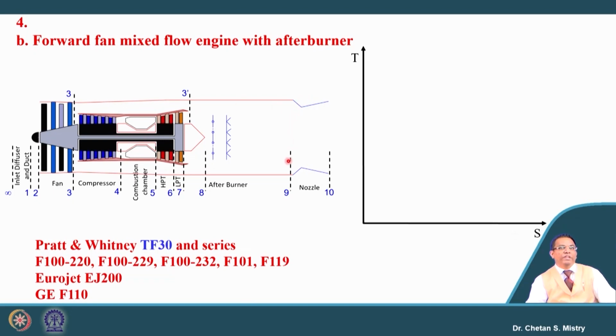So, in place of that, we will try to increase the temperature at the entry of the nozzle in such a way that the expansion that will be happening inside the nozzle will be giving very high velocity. And in this case, we are not having any rotating component, and that is the reason why my metallurgy constraint in terms of turbine blade will not come. Yeah, the afterburner is also ultimately a solid body, there also you need to have some kind of cooling, but the purpose is served with what all we are implementing with the afterburner.